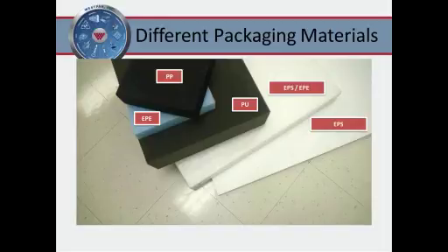And then finally, the so-called premium material in the industry for some applications is polypropylene, or expanded polypropylene, because when you expand it, you simply put air into it by various means. But the polypropylene winds up being an extremely durable material. A lot of the automobile bumpers used to be made out of polypropylene. Some still are. So it's a very durable material, not too often used in packaging applications just because it's too expensive. But the EPS and the copolymers, polyurethane, especially the polyethylene foam, are very common in packaging.